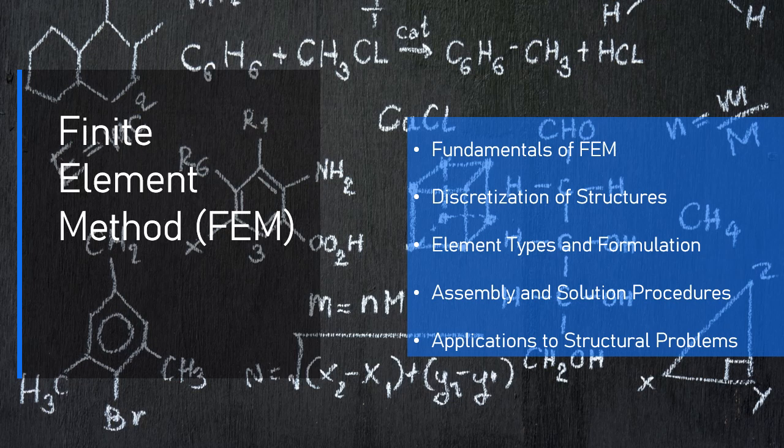2. Material nonlinear analysis. In material nonlinear analysis, the material properties of a structure are assumed to change with stress or strain. This can include plasticity, creep, or viscoelastic behavior. Application example: evaluating the plastic deformation in a steel frame under extreme loading, e.g., a building exposed to a blast or heavy impact. Benefits: accounts for yielding and plastic flow beyond the material's elastic limit. Models failure criteria, such as the onset of cracks or material rupture.